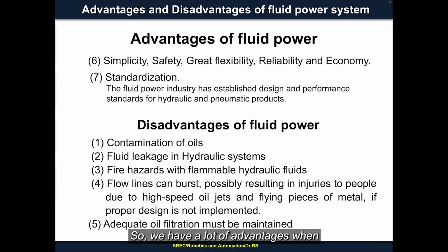So we have a lot of advantages when we go for fluid power compared to mechanical and electrical. In fluid power, we don't have mechanical linkages, so it is easier to do power transmission over long distance. Then it can be easily and accurately controlled, reversibly, and you can infinitely vary the speed and load. Then you can have accurate position control for linear and rotary elements in both hydraulics and pneumatics. Then it is a compact system with a low power to weight ratio. Then we have self lubricating and self cooling properties in fluid power.